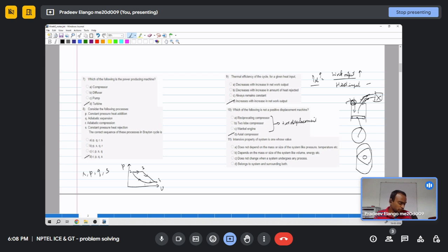So this lobe will keep rotating in an eccentric way, and there will be inlet and outlet, inlet air, outlet air. First, air comes in when the Wankel rotor rotates, and then at the second stage it will come here. So here was the intake, the intake is closed, and now it gets compressed here as this rotates. Similarly, there will be a spark plug here, and then expansion occurs at this region, and gas goes out. I'm not able to draw it properly, so if you see the image, we'll get to know.